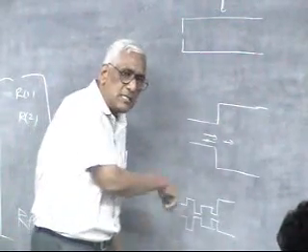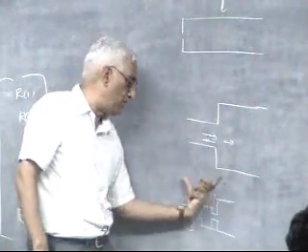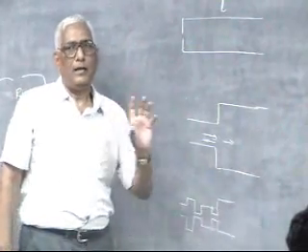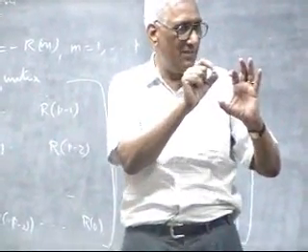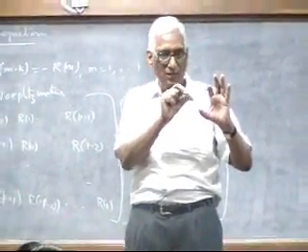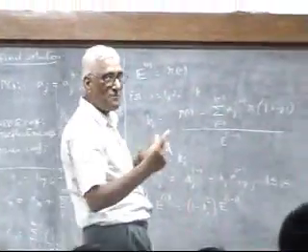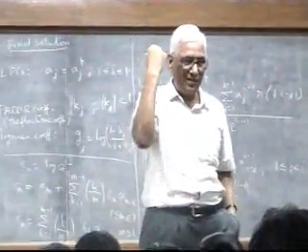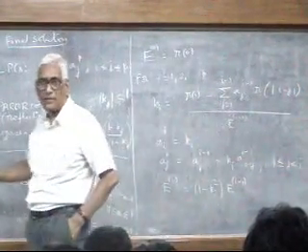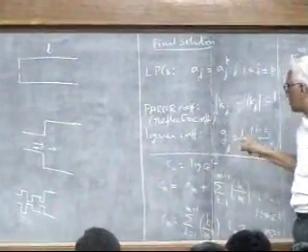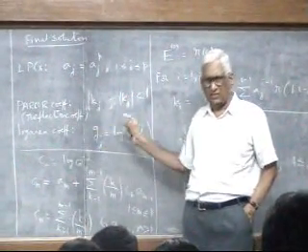You see. So, what is interesting here? From the K's you can in principle derive, for the same total length, the approximate areas where the change in the area causes the reflection coefficient. So, given the reflection coefficient, I can approximately construct an approximation to the shape of the vocal tract. You can see where linear prediction gives an approximation to the vocal tract. So beautifully it comes, and you understand what I am saying. Of course, I am not going to detail that.